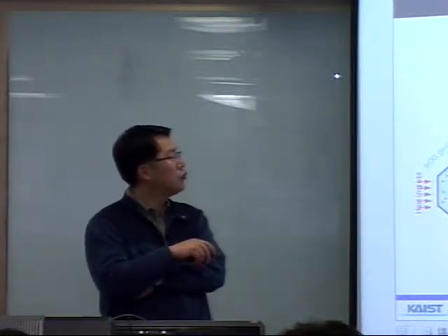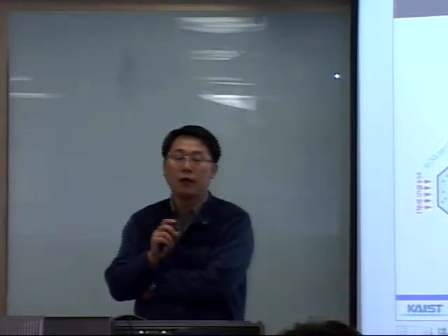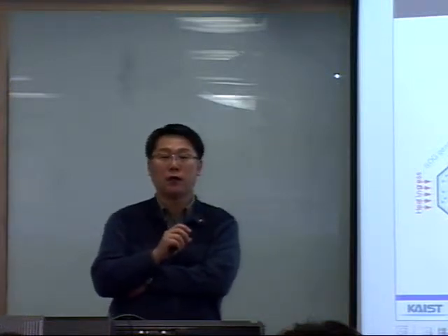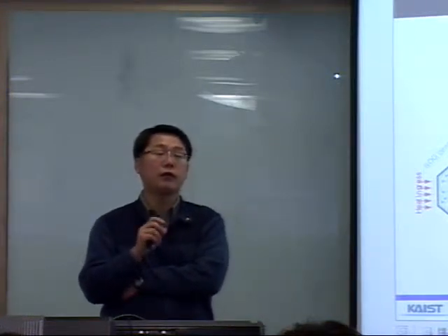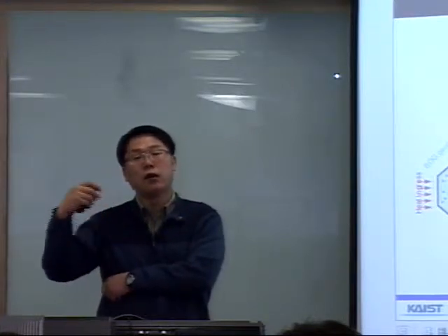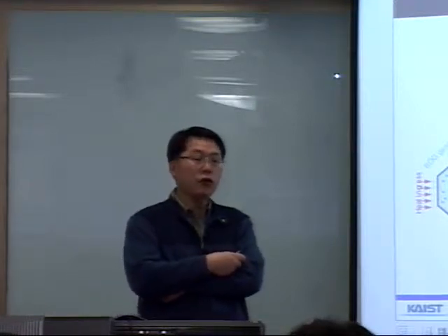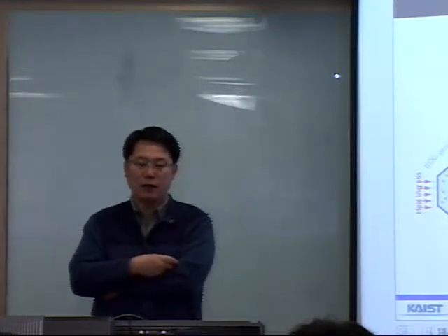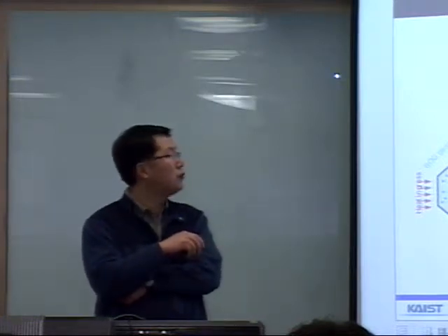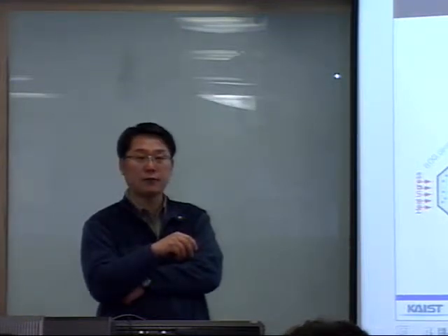And historically, this VOG has been used for fuel. Fuel for the boiler, and the boiler generates steam. The steam drives the steam turbine. The steam turbine drives the propeller. But nowadays, a new concept was introduced, that is to liquefy this VOG using the reliquefaction system.